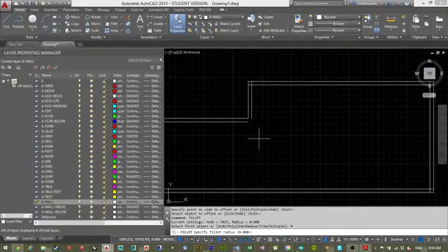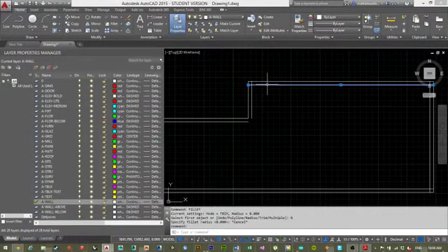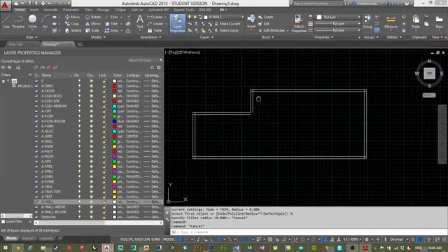But the problem is, if you round the edge with something like 0.005, it would round the edge so small that you can't see it, but it would leave a line, a little curve, and then another line. So you have all these little dots of half circles everywhere. If you forget about them and you want to delete this line, you can delete all your lines, but there's still this little curve there.